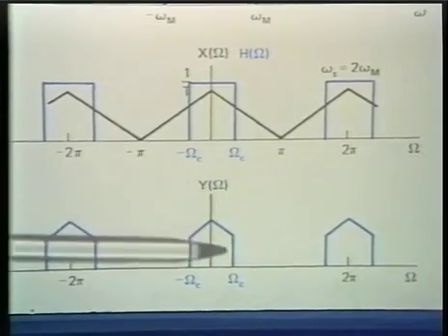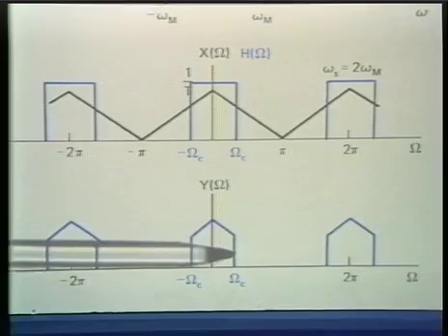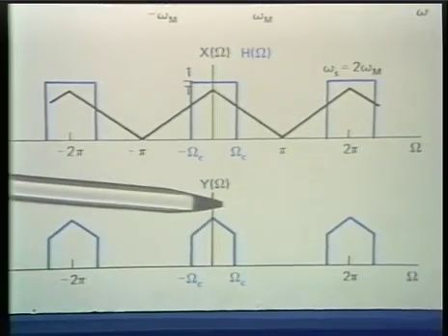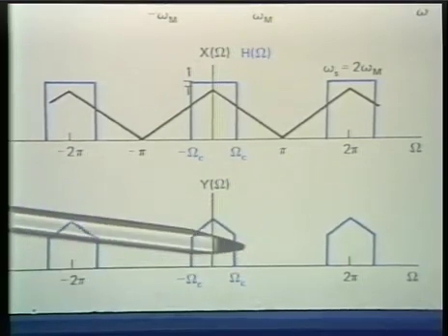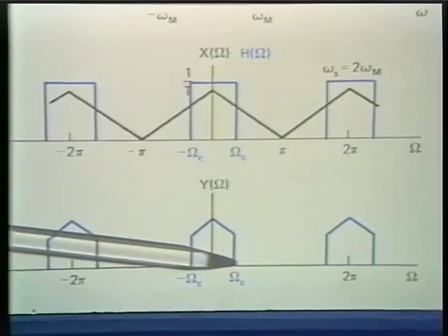And, for example, if this was a third, then if I downsampled by a factor of 3, I would fill up the entire band with this energy. But since I've done some additional low-pass filtering, as I indicate here, there's no problem with aliasing.